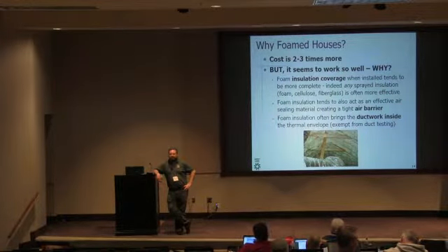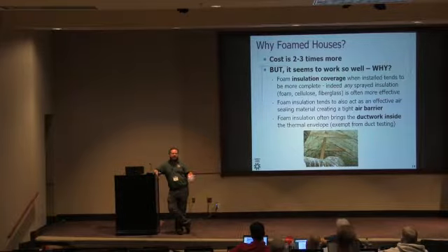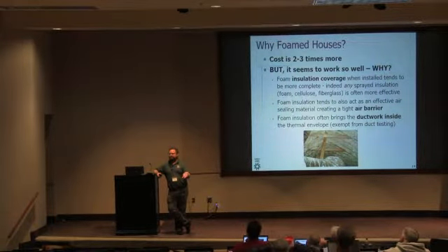Honestly, the real answer is to set yourself up for success. If you want to do an insulated ceiling and you have a crawl space, if that was my house and I was building a new house and I was going to insulate the ceiling and I had a crawl space, I would put my duct system and my air handler in the crawl space. I would do a sealed crawl and I would insulate those crawl space walls. It's a great operating condition. You're ground coupled. That ground coupling helps cool the house. It's actually a free cooling feature. The equipment is going to operate really efficiently down there because it's going to be a pretty steady operating temperature for that equipment to be located down there.